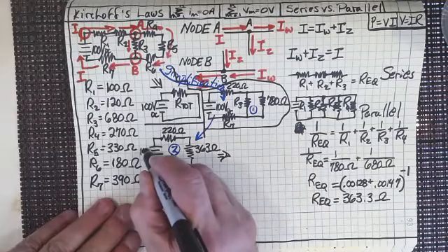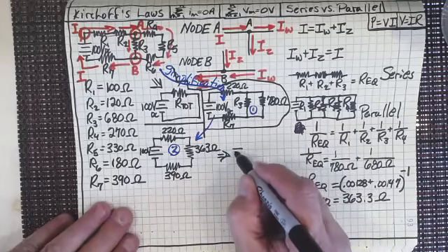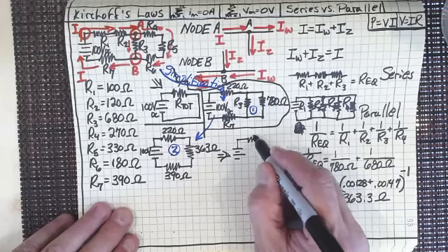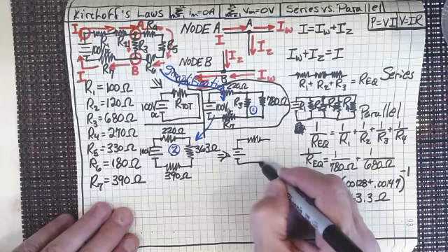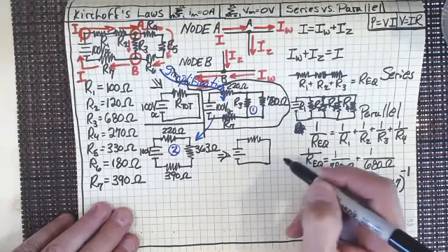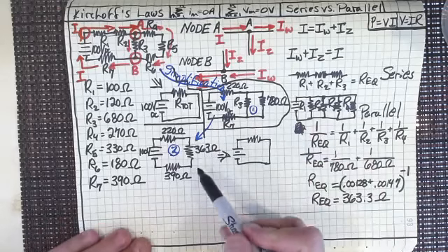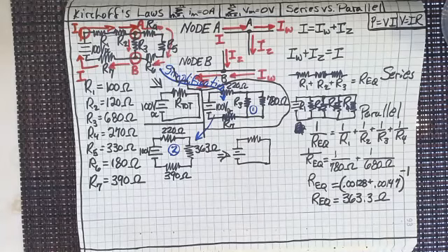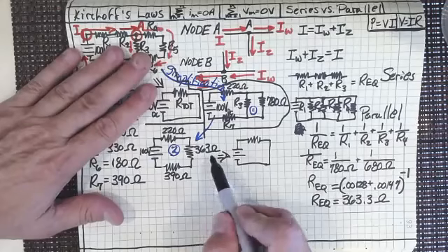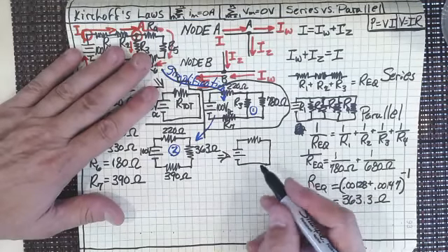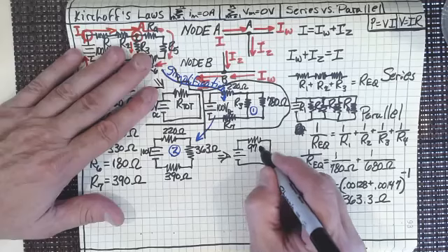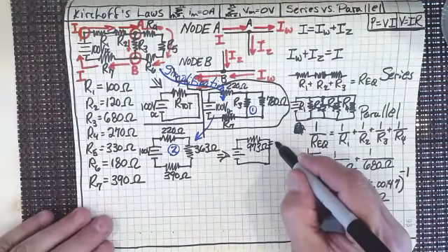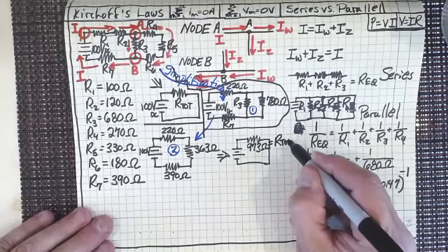Well, let's not forget our 100 volts DC. So let's draw our last circuit, and that's with the 1 resistor, isn't it? And that's going to be our total resistance. So 220 and 390 gives me 610. 610 and 363 gives me 973. 973 ohms. That's the total or equivalent resistance of that circuit.